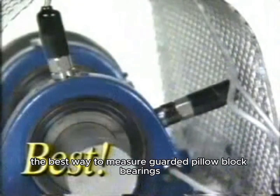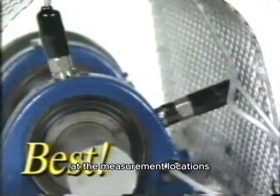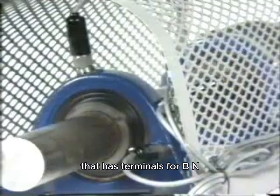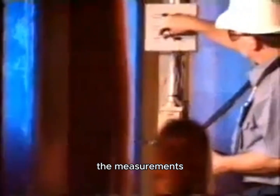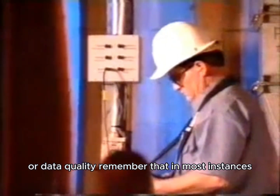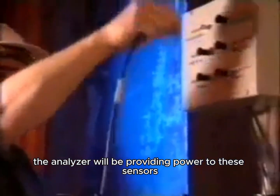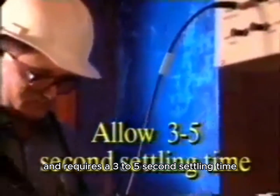The best way to measure guarded pillow block bearings is to install permanent sensors at the measurement locations. These sensors are then wired into a panel that has terminals for BNC cable connections. The measurements can be made without compromising safety or data quality. Remember that in most instances, the analyzer will be providing power to these sensors, and that the sensor receives an electrical shock and requires a 3 to 5 second settling time.